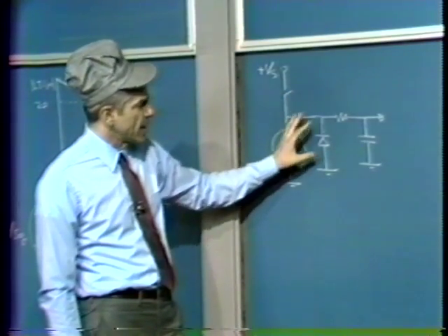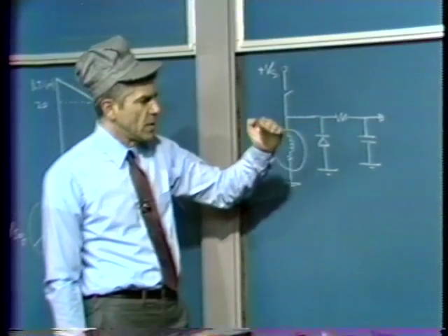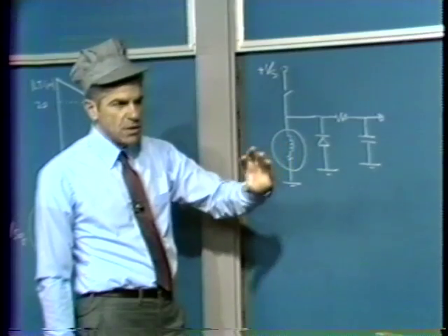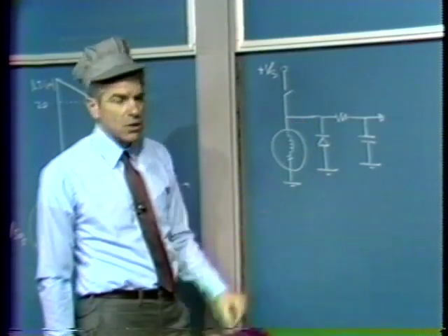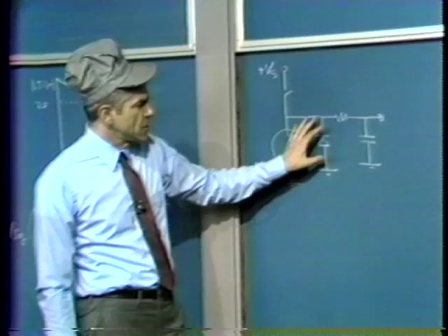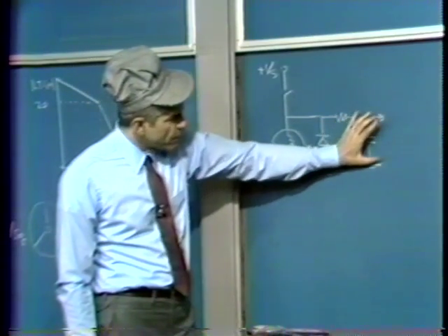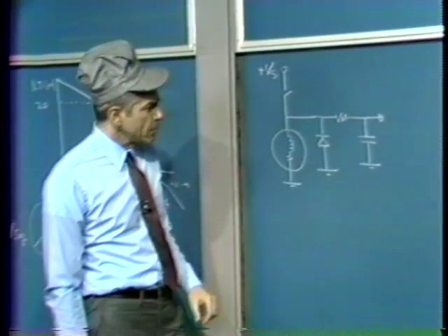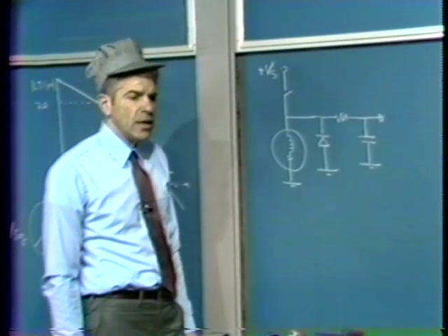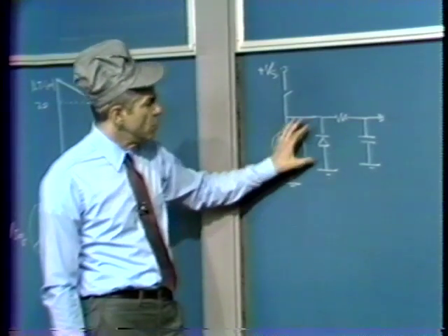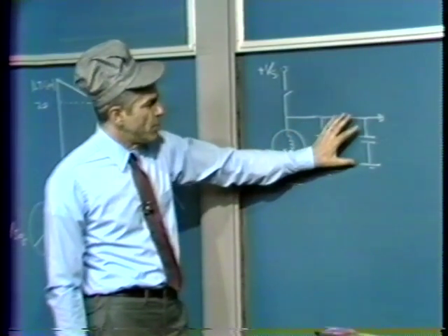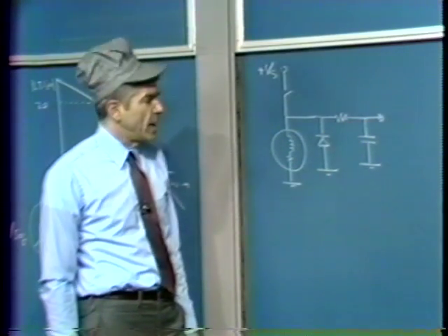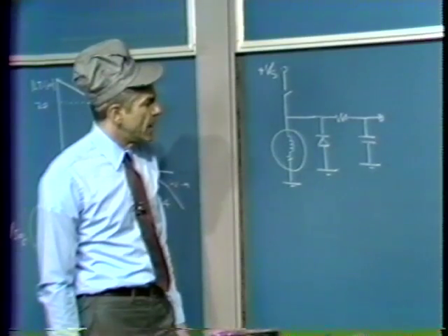The thing flies back. You have basically 0 volts here. The capacitor voltage begins to ramp down. Again, you exceed the other transition point on the Schmitt trigger. Once again, close the switch. So you build a free-running oscillator by going from this output through a Schmitt trigger back to the switch. And if you go through the numbers associated with that loop, you find out that of course the loop works to force the average voltage on the capacitor to be proportional to the command. So that's the way I do the power amplifier.